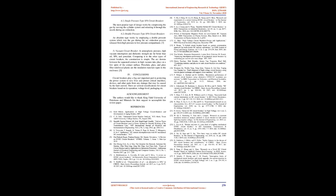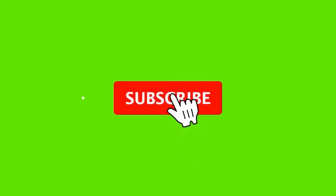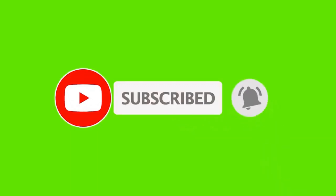4. SF6 circuit breaker. The main advantages are that they have good arc quenching property and good dielectric strength. SF6 is a non-flammable, non-toxic, and heavy gas. But SF6 is a greenhouse gas with a huge impact on global warming. It is chemically inert at normal conditions. The dielectric strength is around 2.35 times that of air at atmospheric pressure, which makes SF6 circuit breakers smaller in dimensions and the contact gaps shorter. SF6 circuit breakers are suitable for the 3.3 kV to 765 kV voltage range and preferred for 132 kV and above.